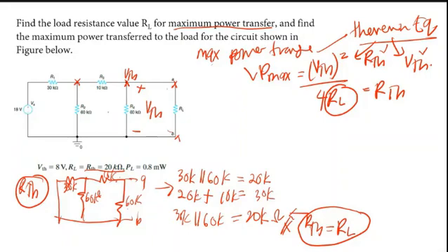But for me, it's easier whether you use the mesh, or the node, or even the series and parallel resistor equation method. But here I like to use what we call the node voltage. Because the VTH is here, and then here you put it as V1. So you will get the equation to calculate for VTH. For the V1 equation, just make it all leaving the node again.